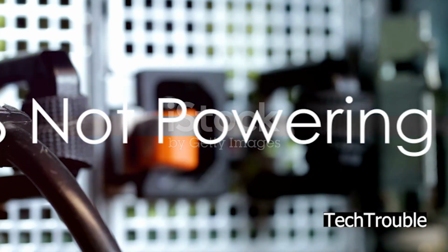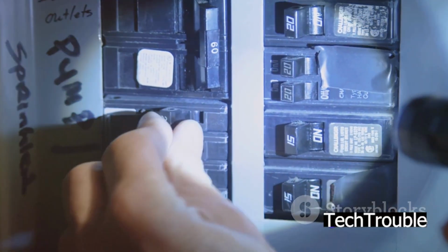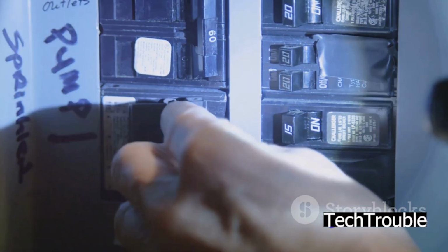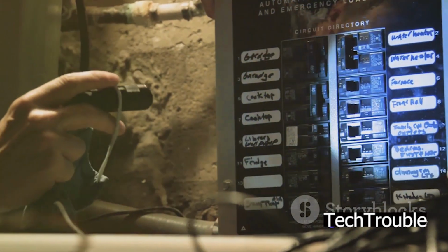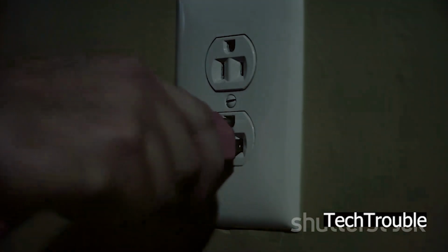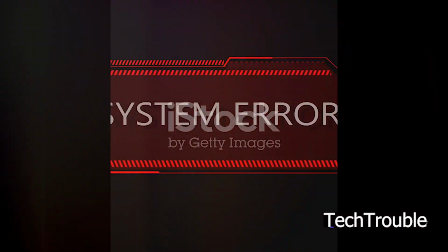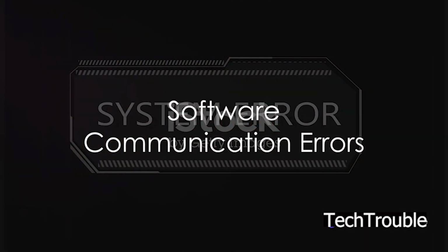But what if your UPS isn't powering on? If your UPS isn't turning on, check for tripped circuit breakers or blown fuses. Reset any tripped breakers and replace blown fuses if necessary. If the UPS still doesn't turn on, try plugging it into a different outlet to rule out potential issues with the power source. Software communication errors are also common.